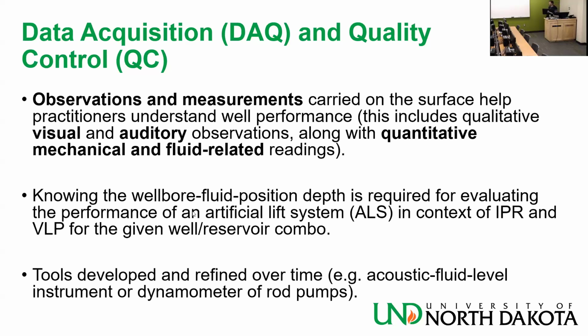If you remember in drilling, we did something called static fluid level, which is basically how deep in the well my fluid can be so that it balances the reservoir formation pore pressure. This one is a little bit different. I stop pumping, I stop flowing my well, and the fluid level stabilizes inside the well, which suggests to me I do not have energy. The reservoir does not have energy to bring this to the surface.